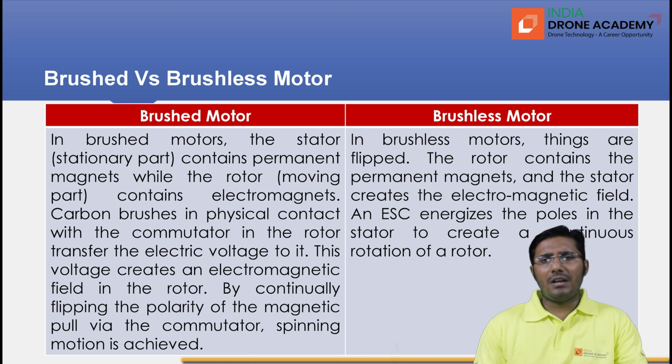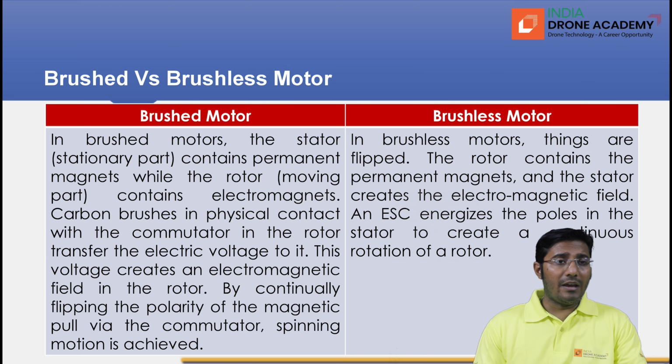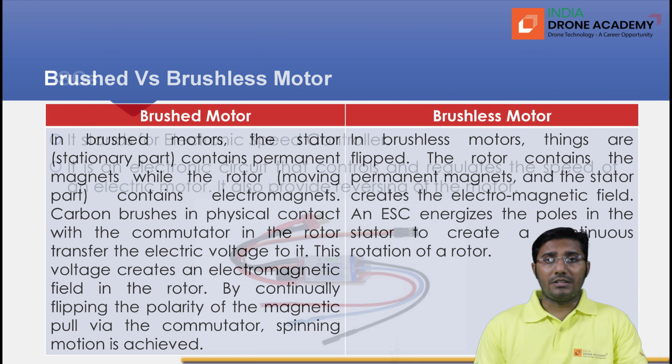After the stator gets energized, the north and south poles of the rotor get attracted by the poles of the stator, and so the rotor rotates. The continuous motion of the rotor is obtained by making use of several poles or coil windings, and by how these windings inside the stator are energized.